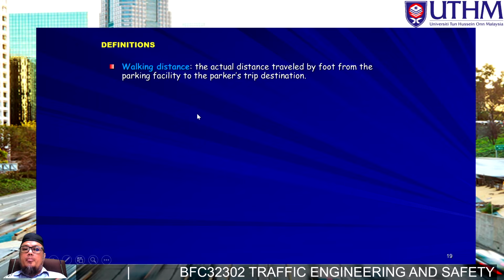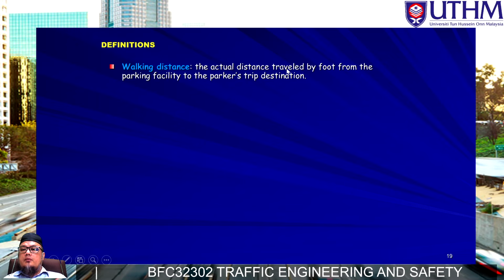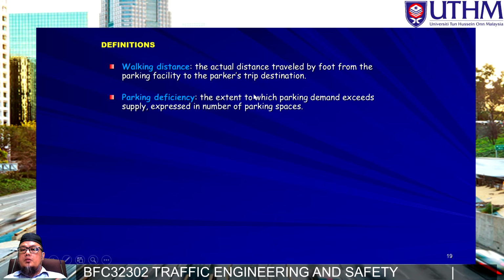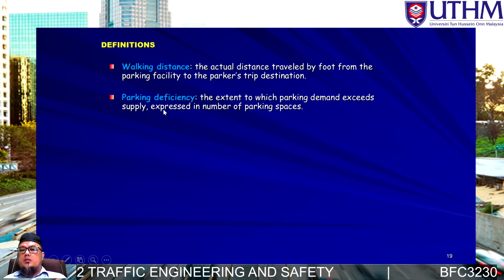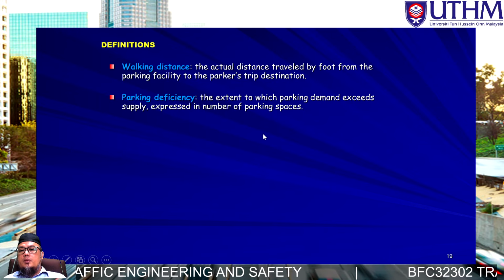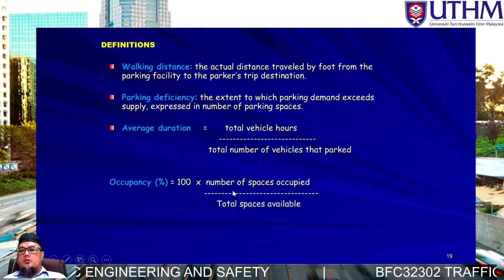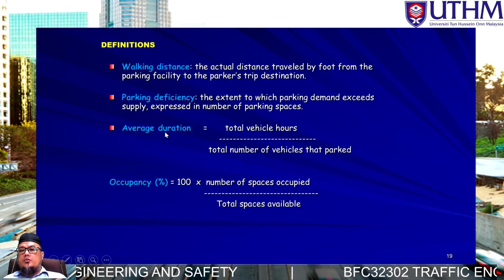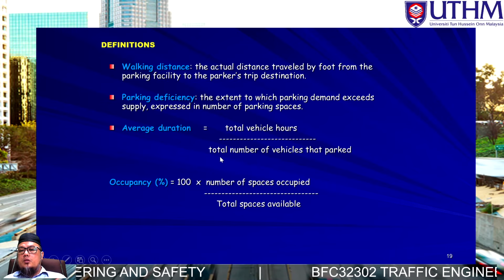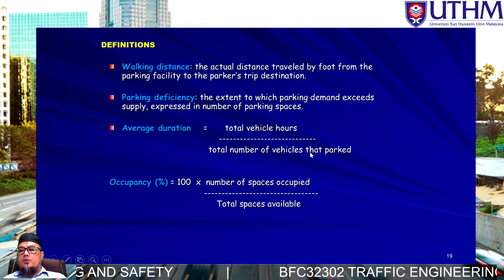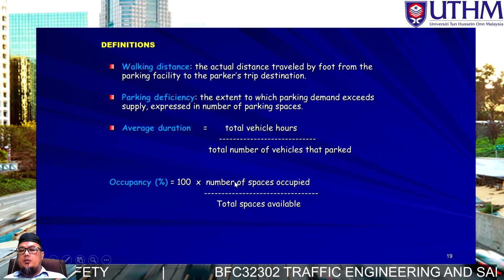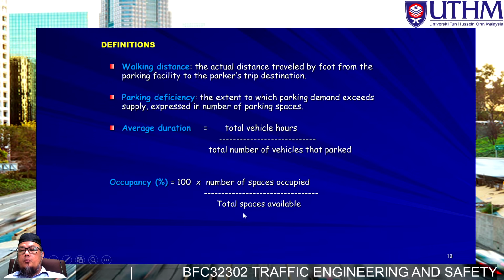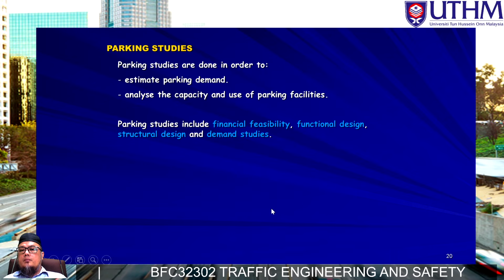Okay, walking distance, the actual distance traveled by foot from parking facilities to the parker's trip destinations. Okay, parking efficiency, the extent to which parking demand exceeds the supply, expressed in number of parking spaces. Okay, last one is average duration: total vehicle hours, total number of vehicles parked, and occupancy, which we measure as percent, number of spaces occupied over total space available.